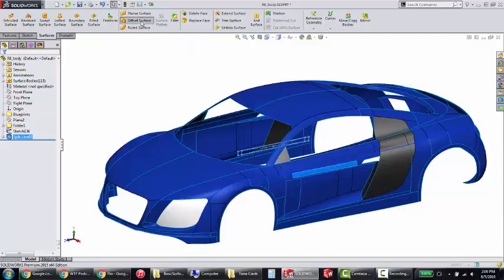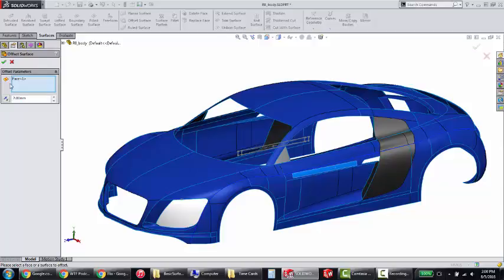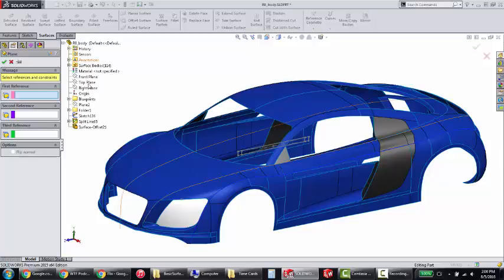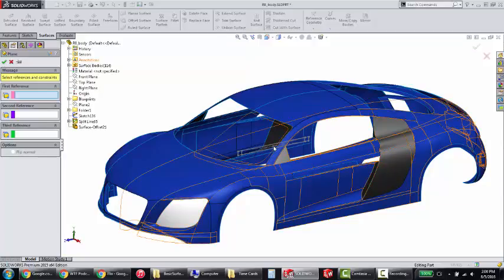Next thing I'm going to do is offset where I'd like the height of the character line to go up to. In this case I'm going to do a 7mm offset, and then I need to basically draw a 3D line of where that is. So I'm going to create a plane. It's right in the middle of where I broke up that face.